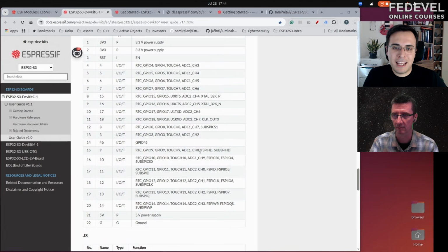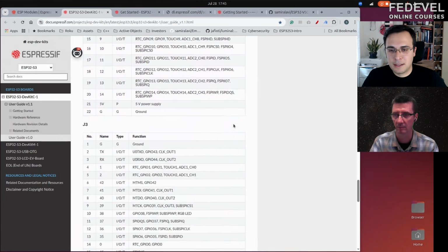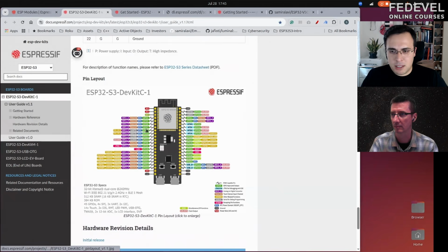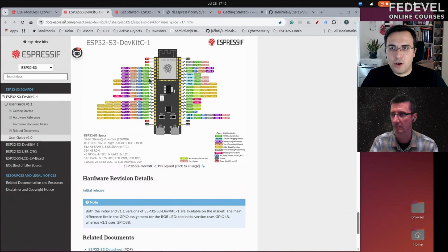The naming of SPI peripherals on ESP32 is a bit misleading, but it basically means there is a main SPI and a secondary SPI, so you can have two SPI interfaces. But when you use the second SPI interface, you lose some of the other functionalities on the pins. So it is up to you to decide which one to use. And yes, the pins are defined here.